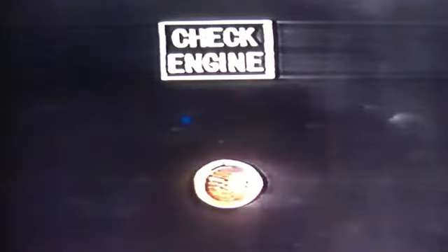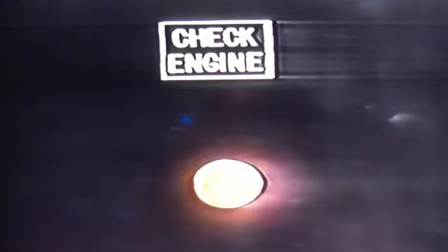To give you an idea how this would work in the real world, we've stored some trouble codes in the ECM of our test engine. The ALDL on the test engine has been moved up here, since we don't have a dash to put it behind. It is the 12 terminal type, and we've jumpered these 2 terminals. Now, let's see what the computer tells us. We see a 1 flash, 2 flash sequence, a 12 code, which indicates the computer has diagnostic capability.